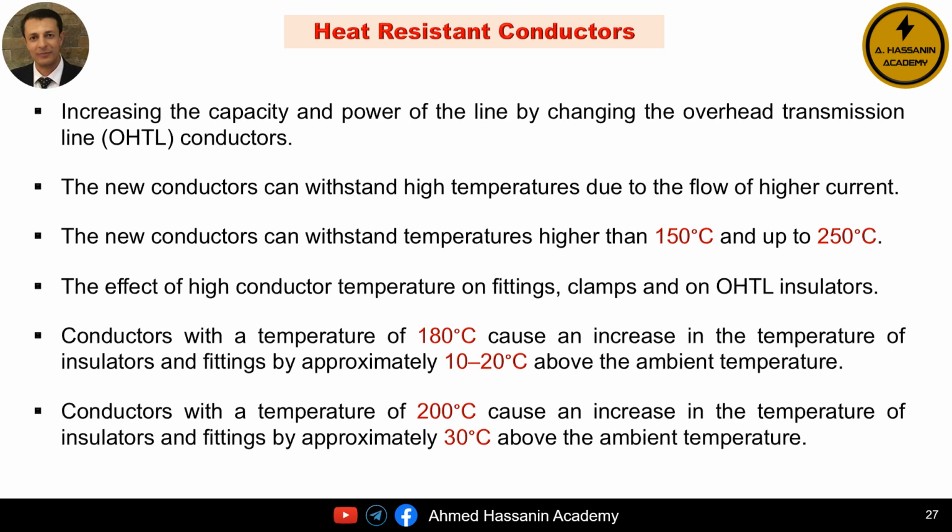Does the use of heat-resistant conductors, which may reach temperatures of 150 degrees Celsius or even more than 210 degrees Celsius, affect the insulators, clamps, and other accessories of the overhead line? Of course, the answer is yes. All components and accessories of the overhead line will be affected when heat-resistant conductors are used, and the most affected element is the line insulator itself. Therefore, this factor must be taken into careful consideration.